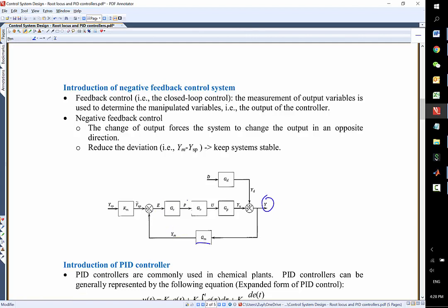And then based on the measured output and the set point value, we're going to control, in this example, the opening of the valve, and then the flow rate of W2, the inlet flow rate, right? And then control the mass fraction of the output.